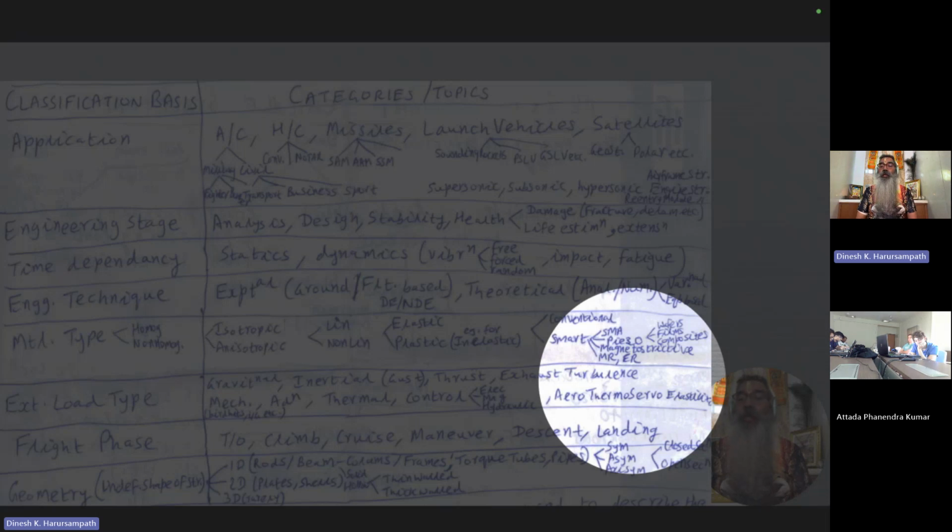And as I already mentioned in a different context earlier, you can't expect to study each of these individually and eventually stitch them together. Because most of them at least are non-linear, especially the aerodynamics, the elasticity, and the control systems that are used today. A lot of non-linear models are there, which are much more accurate and realistic compared to the linear models. Therefore, when you bring them together, the principle of superposition is no longer valid, and you can't just stitch them together. So from right up front, you have to bring them all together.